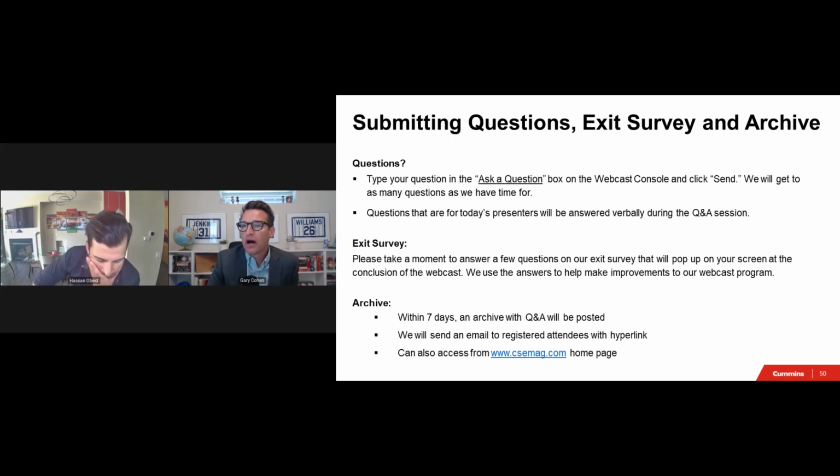Got it. What should be specified to get the best level of short circuit performance available? Okay, so for the short circuit, that's a really good question. What you want to do is the calculations, right? Do your calculation to the best you can. And we know this is not easy. You don't have all the information. So do your calculations and then figure out what is the available fault current at the terminal where the transfer